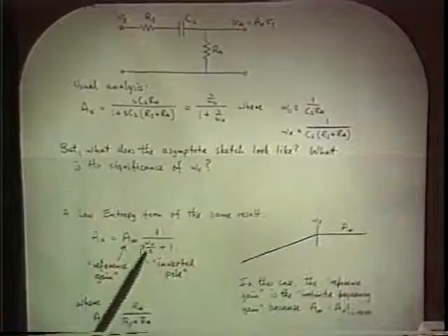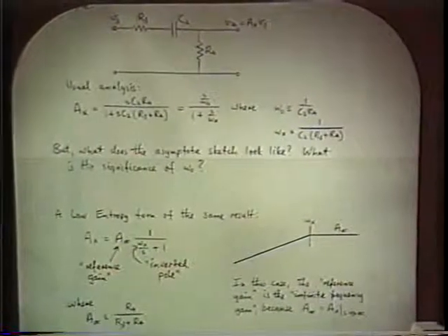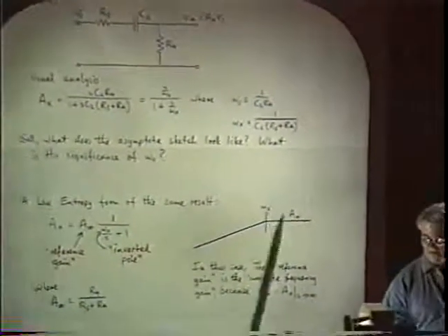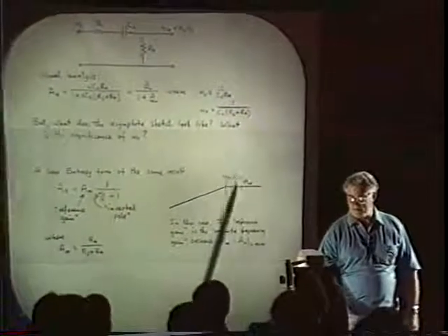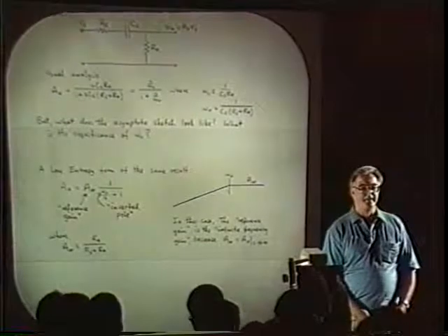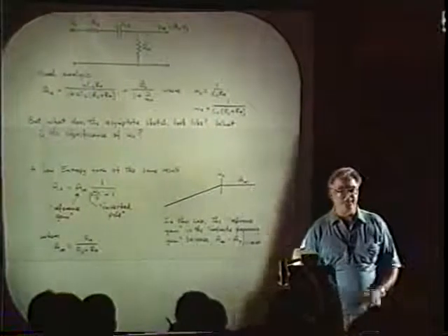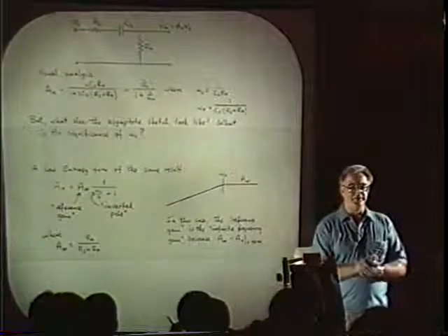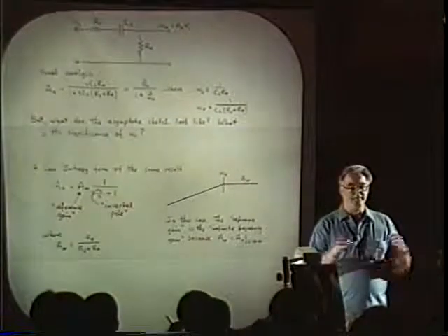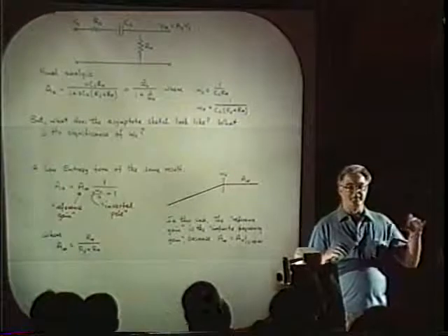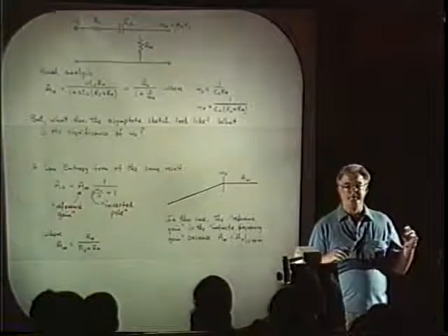So that's what I call an inverted pole. And there's the sketch that goes with it. And that's the only value of doing this, the fact that you can visualize that sketch, because it maintains the complete symmetry now with the two directions of the frequency axis. High frequency poles come about because of shunt capacitances usually.